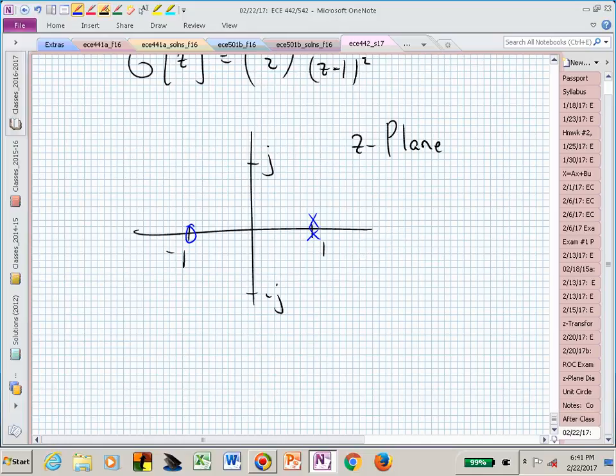But now you can compare this. And what do we know? We know z is equal to e to the sT. Our double integrator had poles at 0 at the origin. We plug in s equals 0. Where are our poles here? e to the 0. 1. So now we have 2 poles at 1. That's consistent with what we would have expected.